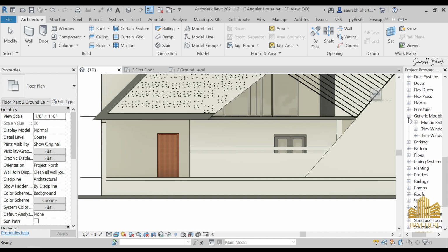Generic model, mullion pattern trim. I just forgot where it is placed. So curtain wall, no, addition, no. We can actually edit the family of it directly, but I cannot find that wall reveal family here. So actually we have to make something out of that one.